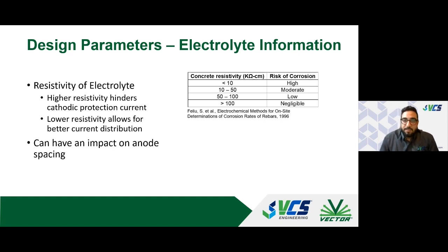With that, resistivity is one of the factors that we look at. If you have very low concrete resistivity values, your risk of corrosion is high. And conversely, if you have very high resistivity values, your risk of corrosion is relatively low, based on previous research that's been done. And resistivity is a double-edged sword, because if you think about it, if you have no corrosion